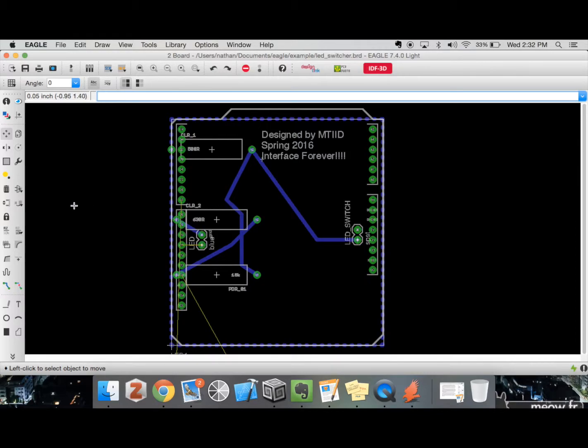So if you do accidentally use those and you find things are connected, but it's still throwing you errors and saying that it's not, you can use the join wire segment to electronically connect those components, even though physically, they actually already are connected.